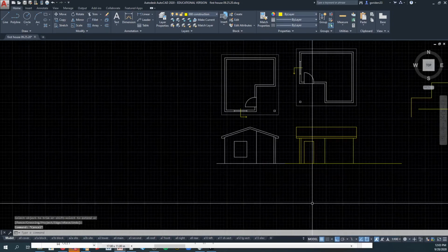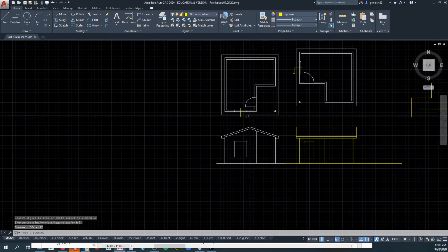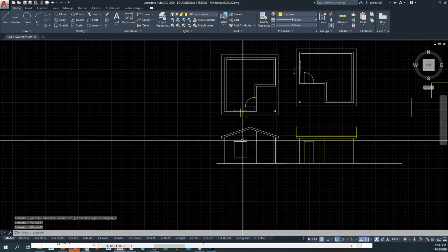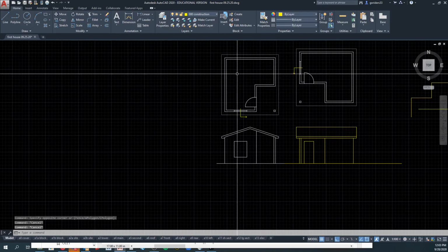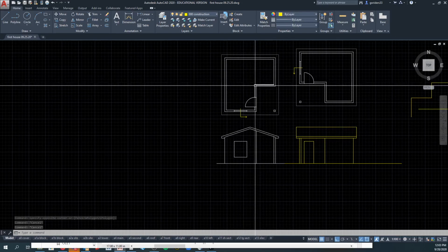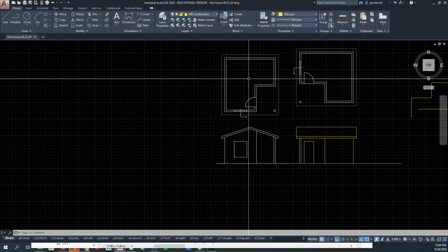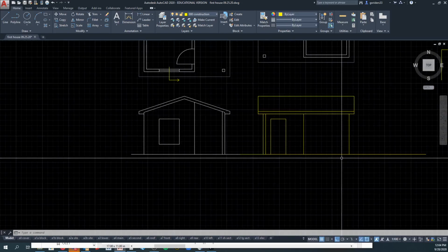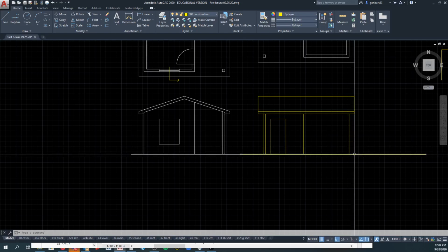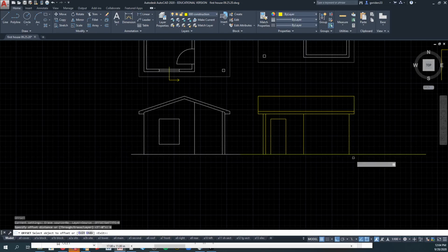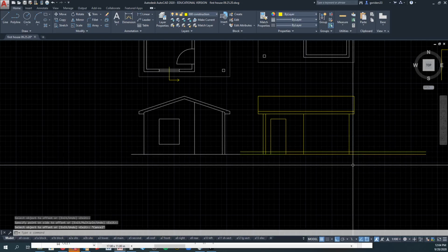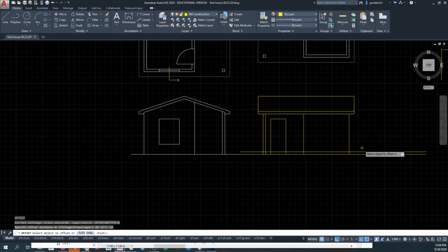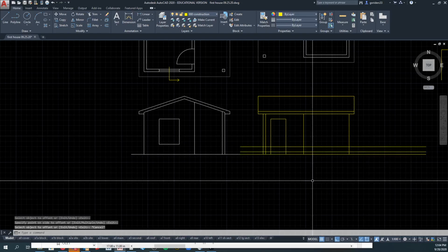There's my side elevation. So what I asked you to do is cut this section. Looking through this window, looking toward the door, I would like you to give a shot at cutting that section. Now the top of the foundation, I want the top of the foundation to be 6 inches above the dirt. So the top of the foundation is 6 inches like this, and then the floor, I'm just offsetting now, the floor is 12 inches. So it'll look something like this.